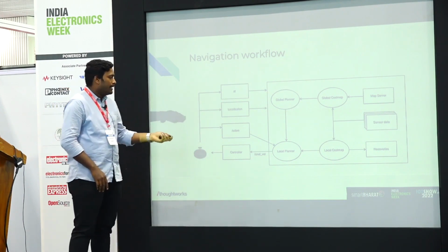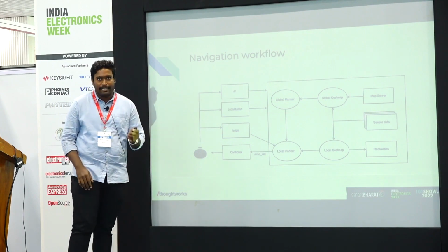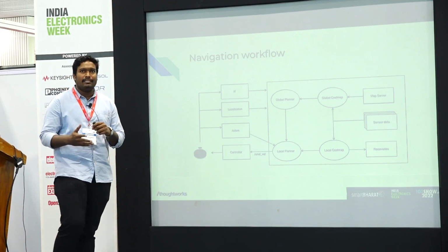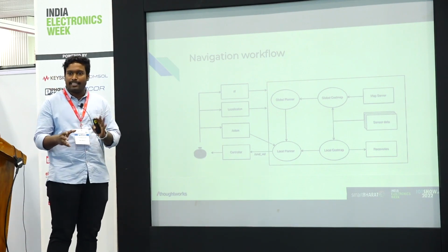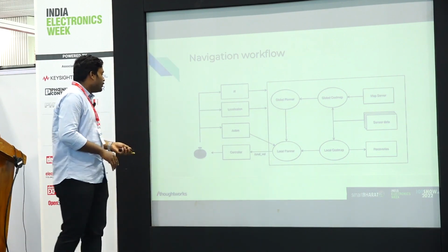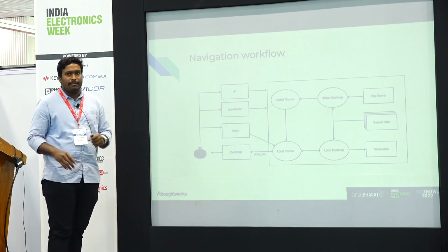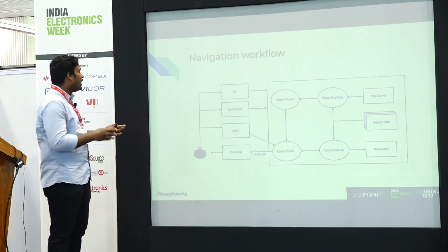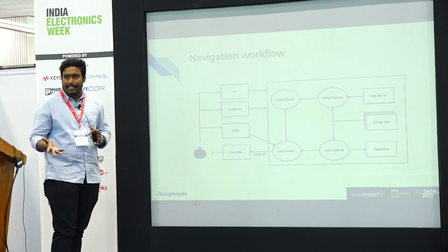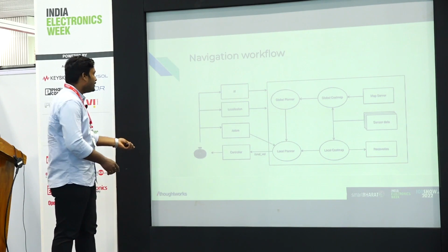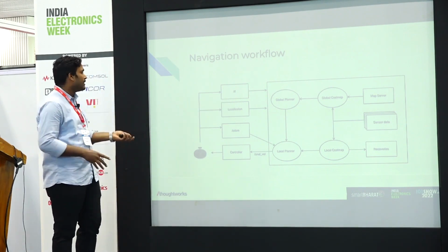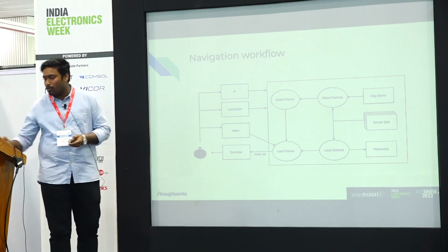Now take a look at the local planner. The local planner just sends commands, the command velocity. Command velocity is a data structure that conveys the linear velocity and angular velocity. Then you have a controller. The controller is a high level hardware abstraction that takes in the data and conveys it to the real hardware, because hardware cannot really understand what you're talking about in software. You also get odometry information for localization and other things. So these are all the things that Harish talked about.